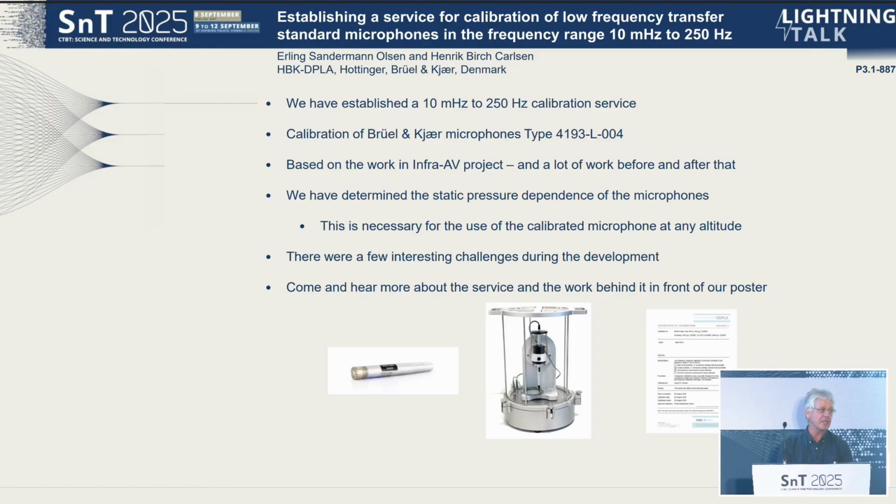and a lot of work before and after that. What we have done is actually extending a service we have had for many years, and we have determined the pressure coefficient in the full frequency range for the microphone so that it's possible to change the calibration values to the altitude where you are using it. And that's very important that you have that correction. There were a few challenges during the development that I talk a little about at the poster. So if you're interested in hearing about the service or the interesting things we made on the way, please come at position 43 and see my poster. Thanks.